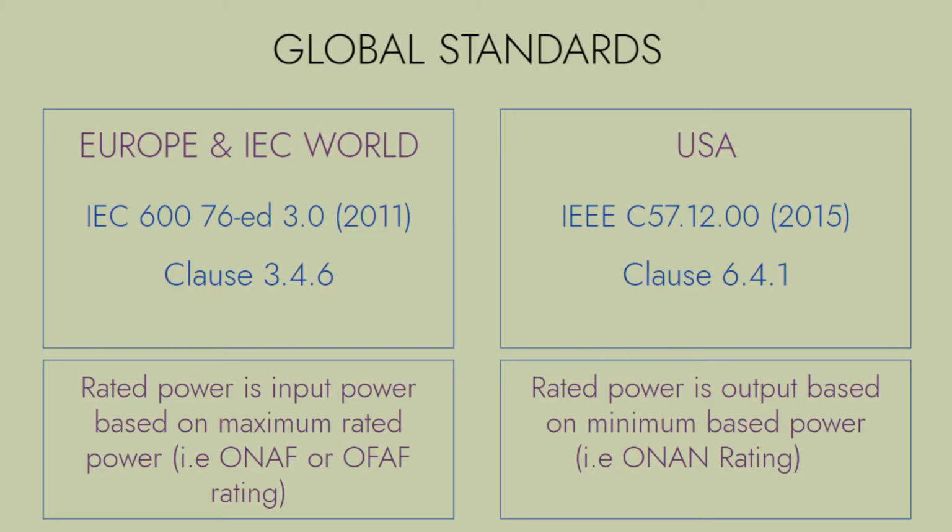So these 3 factors are multiplied to find out the total rating of the transformer, that is total connected load, expected increase in load factor 10 to 25%, then the demand factor multiplied by diversity factor, that decides the rating of the transformer.